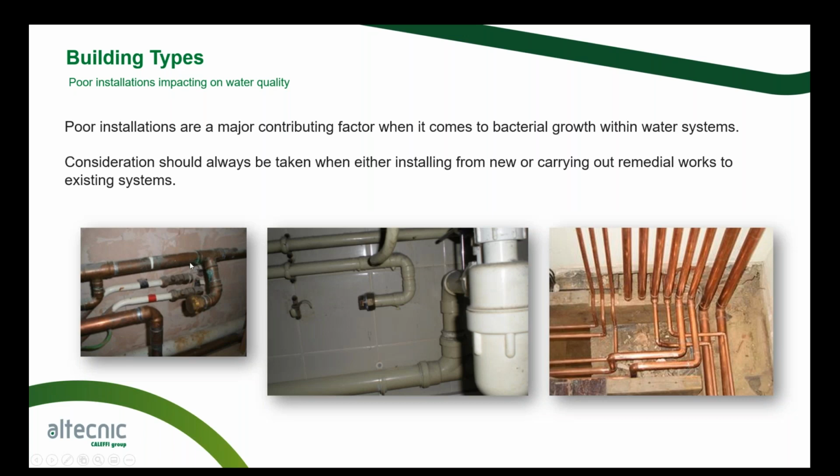This pipe at the top may very well have water flowing through it, but this dead leg is going to have to turn over its water. So if any kind of bacterial growth starts to form within there, it's going to start creating problems around the water system. So wherever we can, it's always important that we remove the dead leg from the system.